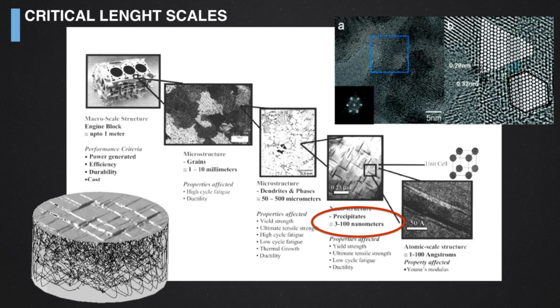An example is when you have a copper wire or an iron wire and you want to break it. So you start to mechanically move it up and down, up and down, up and down. It releases a lot of heat, so if you touch it at the bending point, it can be very hot because it is releasing thermal energy after all the accumulation of the dislocations. And when you reach the critical density of dislocations, it breaks. It becomes brittle because you cannot further generate defects in the structure.